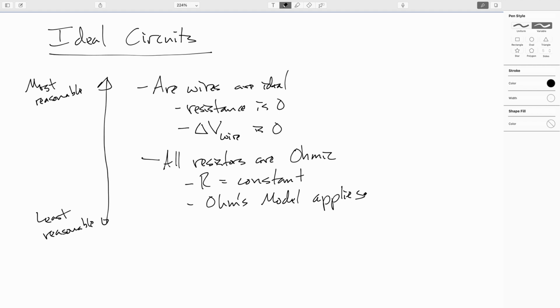Anyway, in this system, the last color that gets painted on indicates the tolerance of the resistor. In other words, to within how many percent is the resistor going to be its stated value. If there is no band, it's 20%. If they do paint bands on, it corresponds to 10 or 5%. There are some extensions to this code to do a little better than that.